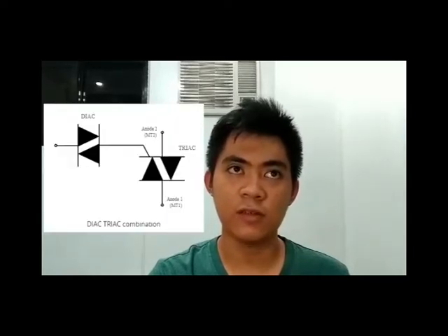Diac applications. One of the major applications of the Diac is with Triacs. It is used in conjunction with Triacs to equalize their switching characteristic. By equalizing the switching characteristic of these Triacs, the level of harmonics generated when switching AC signals can be reduced.